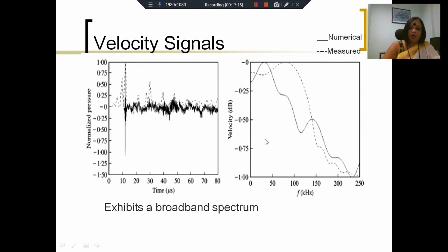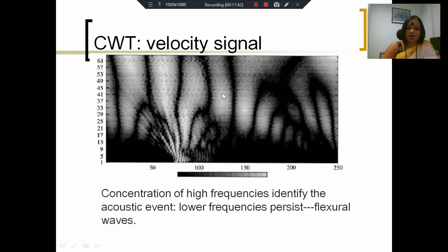If you are at the low frequency range, there will be considerable noise, so therefore we prefer to make measurements at around 150. We can go higher, but if we go to, let's say, 200 kilohertz, the magnitude will diminish, and therefore the signal to noise ratio. The noise may also decrease, so we'll have to see whether the signal to noise ratio is what will decide for you. If even with low amplitude signals the signal to noise ratio is good, we can go to higher frequencies as well. This is something where engineering judgment comes into the picture.